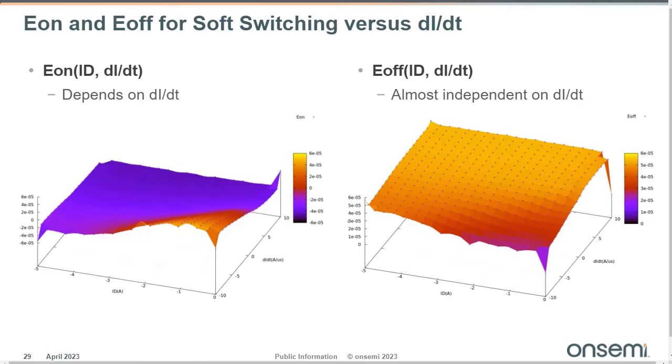This is the purple or blue area, where the energy stored in the output capacitor of the device is released inside the resonant energy and stored in the other device to turn off the other device. But in between, you have resistors that will generate losses, and this is why we can say that during soft switching we have zero losses. Yes and no, because we always have resistor losses, and this is what we will capture through the parasitics inside this simulation to obtain the model.